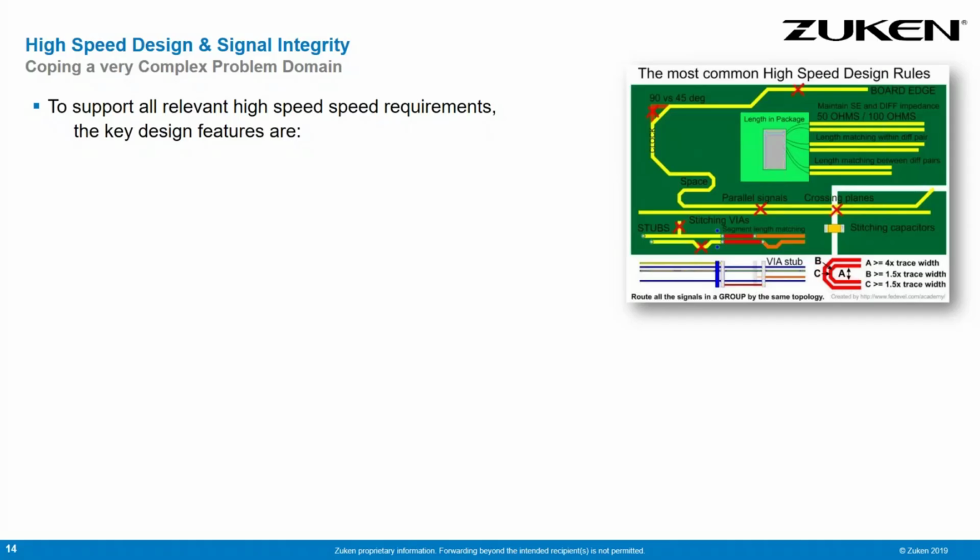These days we have differential pairs everywhere. We have differential clocks and the strobe signals for DDR. We have differential interconnect structures for SATA, for HDMI, for DVI. So we have all these weird routing rules. In complex ICs, like an FPGA, often based on the package, we have different trace lengths from the ball to the die, which we have to adjust somewhere on the board. We have rules like it's forbidden to cross a split in the underneath reference plane. We have length adjustment or stub length rules.